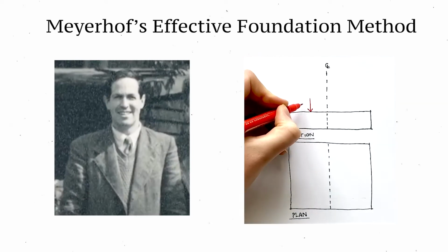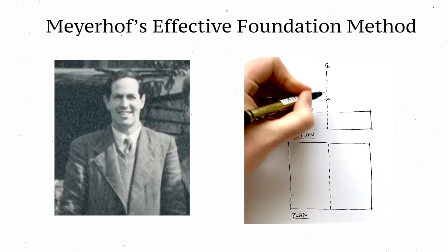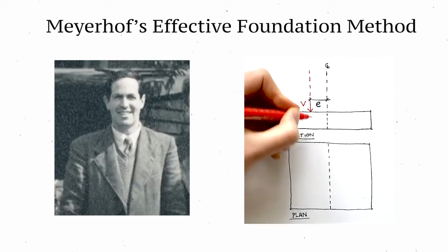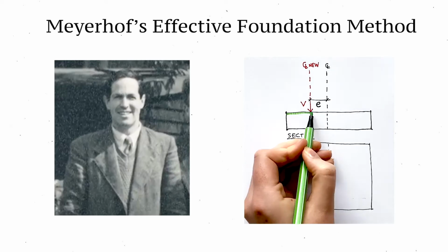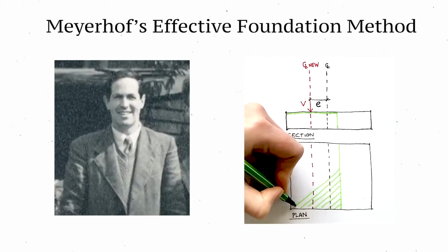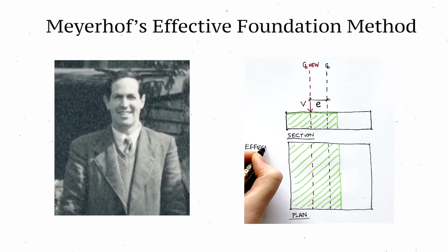Meyerhof modelled the eccentrically loaded foundation by assuming the vertical load now acts at the centroid of a new reduced foundation size, known as the effective foundation.